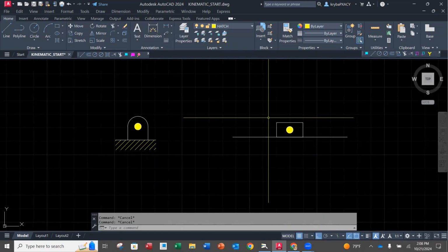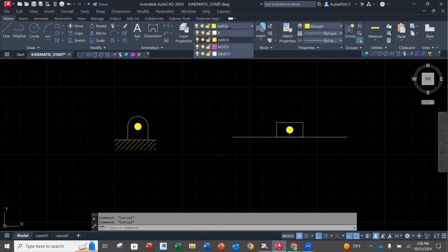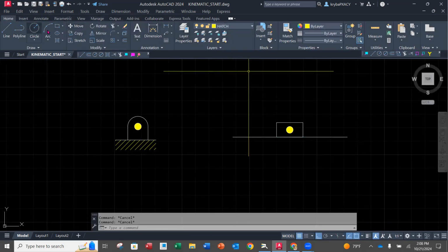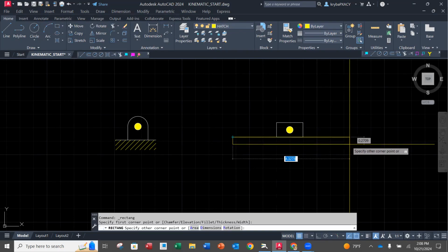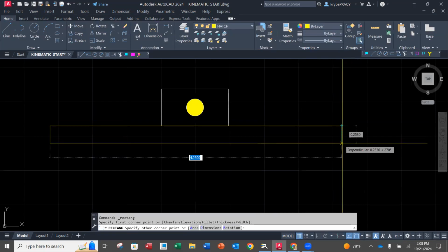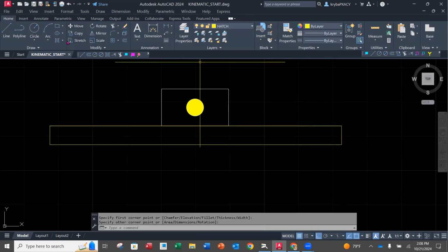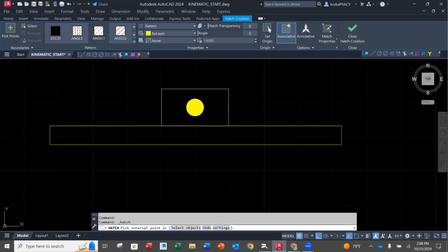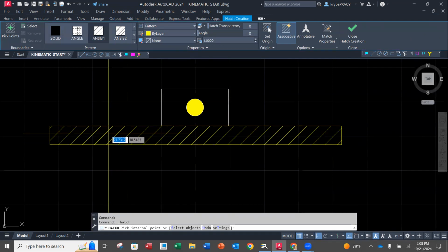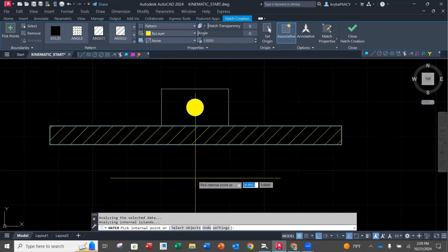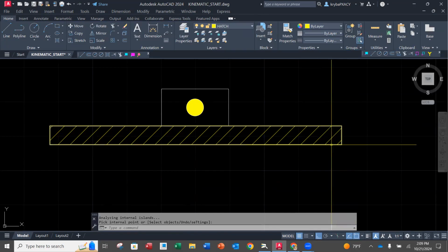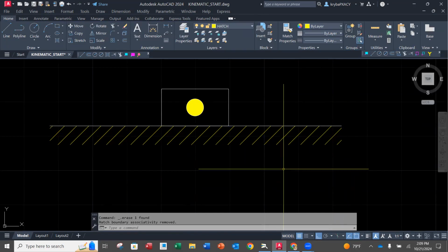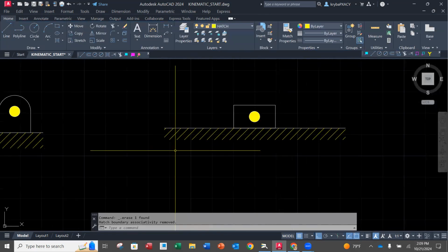Okay. And now I'm going to create another rectangle. I'm going to leave it on the hatch layer. I'm going to create another rectangle so that it's underneath here for about that same, activate that corner, right about there. And now we're going to do that same hatching, this time back to the ANSI 31 or ANSI 131. Click on that. Scale of 1. Okay. And then I'm going to select the outside of that rectangle and I'm going to delete it so it looks like this. Okay.